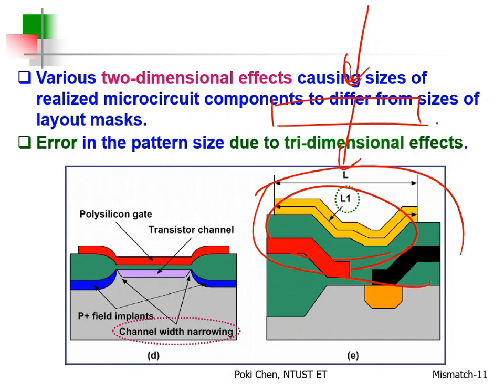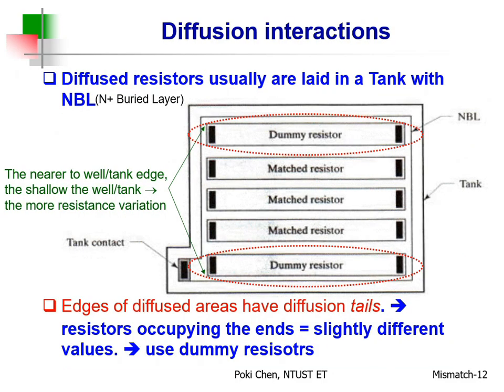If for the first one, L1, it needs to go here and downward to the bottom, then back to the top, you had better make L2 exactly the same environment. L2 also comes from here downward to the bottom, then goes back to the top. That's it. Okay? Please keep this in mind. Otherwise, after fabrication, or even before fabrication, they are already different. They won't be matched. Okay?